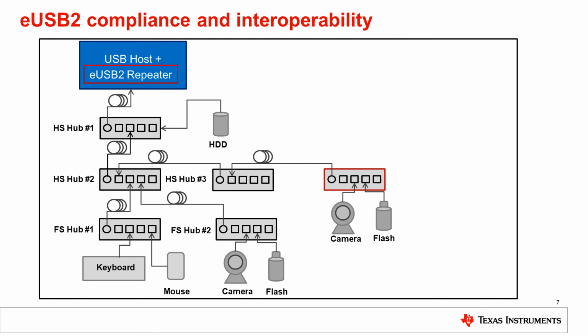In the modified interoperability tree shown here, the host implements an eUSB2 repeater, and the tree is simply reduced by one hub tier. All the same device speeds, traffic, and cable lengths remain the same. Likewise, when running USB 2.0 electrical compliance, an eUSB2 repeater would act similar to a hub, with packets having allowable end-of-packet dribble and drop synchronization bits at the beginning of each packet.